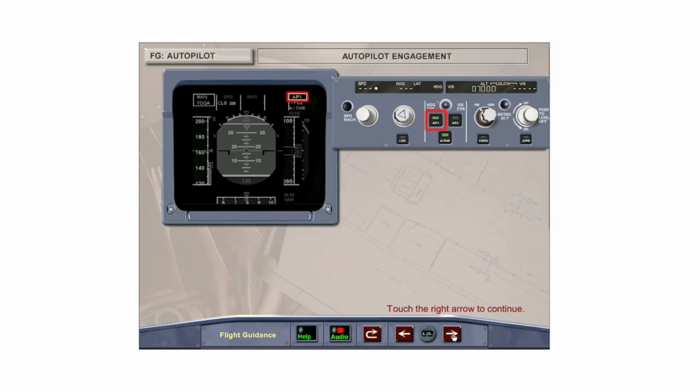The autopilot can be engaged after the aircraft has been in the air for at least 5 seconds by selecting either the Autopilot 1 or 2 push button on. When an autopilot is engaged, the light on the Autopilot push button illuminates in green, and the FMAs display Autopilot 1 or Autopilot 2 in white, corresponding to the engaged autopilot.